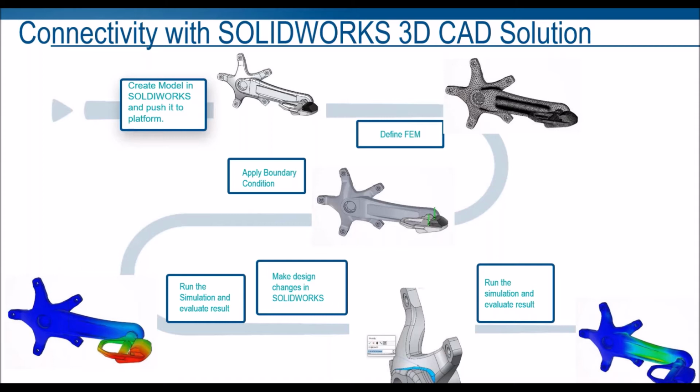We'll create the FEM. It stands for Finite Element Meshing representation, which includes the mesh, its cross section, and the type, whether it is a solid element or a shell element. And then we can also define the material in the same. Apart from that, we also define the connection, how the components are going to interact, whether they are totally bonded or there is any clearance or friction going to happen between them.